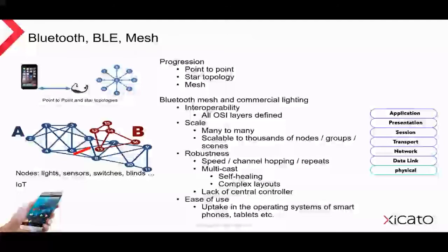With respect to robustness then, Bluetooth mesh transmits messages throughout the network. So if one node is disabled, the message will still get through. The removal of a central controller means that there's no single point of failure within the control system. A Bluetooth mesh network uses multicast, multipath transmission, so messages can quickly reach all corners of a network with low latency, regardless of where they originate.